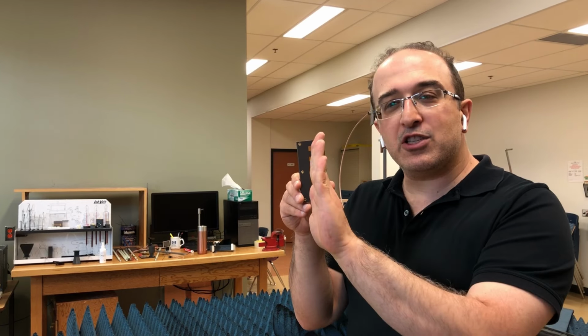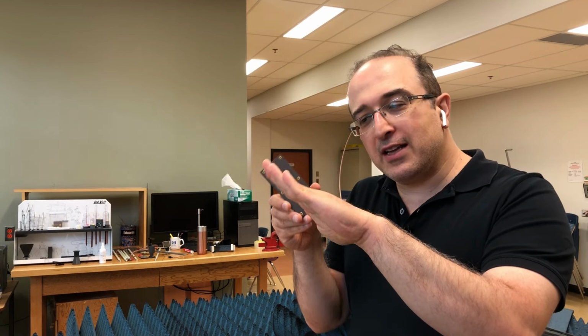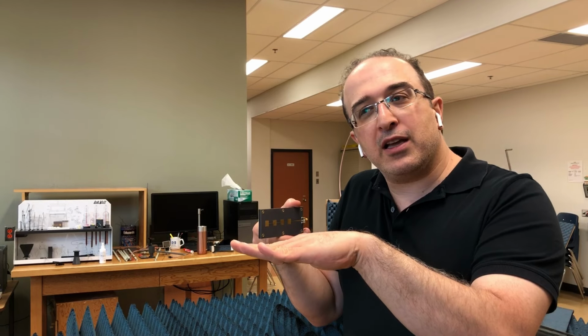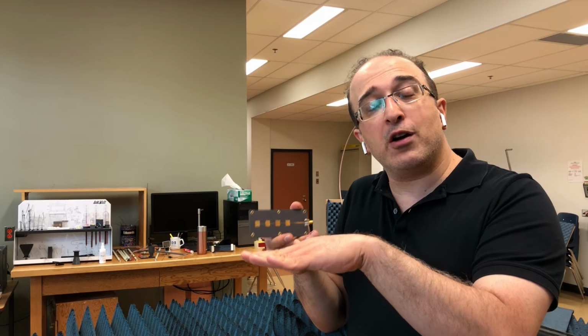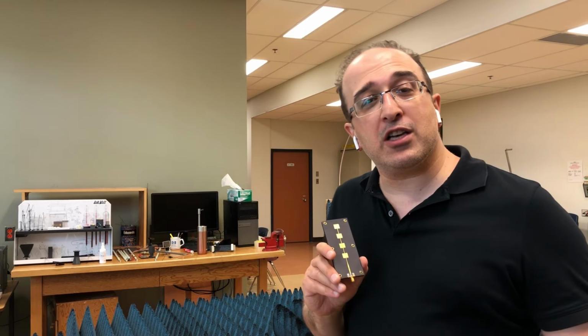Now, if I go to E plane, which is this plane, I cannot rotate my antenna in this plane. So what I'm going to do is a trick. I'm going to rotate it 90 degrees like that. Now it's going to be E-plane. But remember, now the polarization is horizontal. So you want to rotate your horn antenna also 90 degrees so that you can measure copole E-plane. We're going to first do an H-plane data acquisition, then an E-plane data acquisition, and then compare them together.